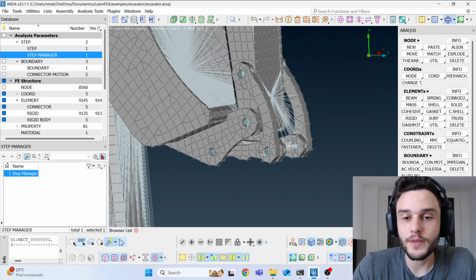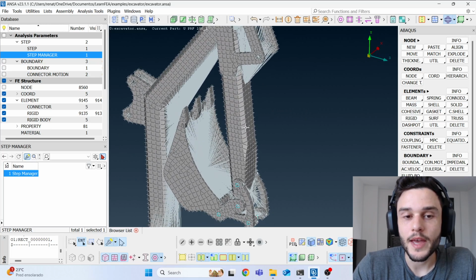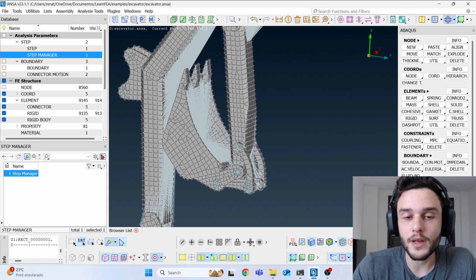Probably the x-axis of each coordinate system is not completely parallel to the others, which means that there is going to be some misalignment, and therefore, when we apply these rotations, there is going to be an attempt to deform the rigid bodies. This is the issue, because the rigid bodies cannot deform, and therefore there is this attempt of deformation, but it's not possible, and for that reason the software is not able to converge.